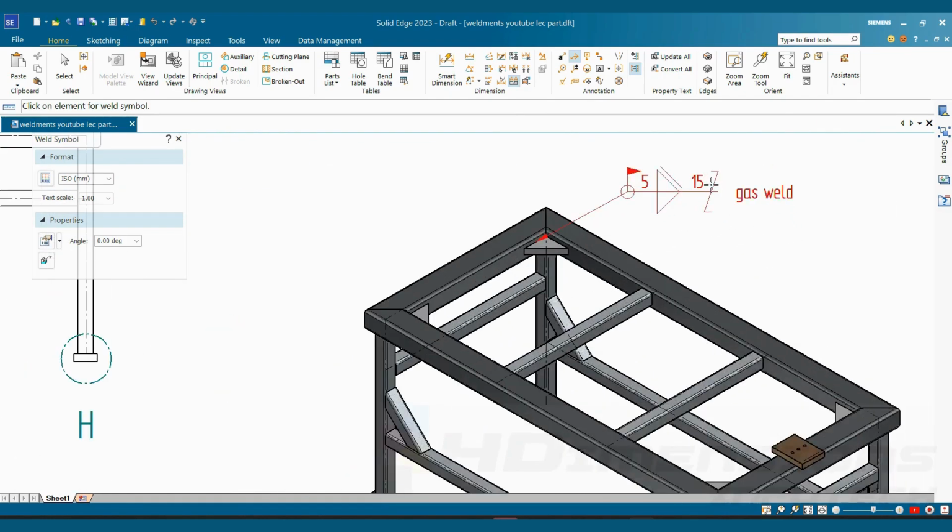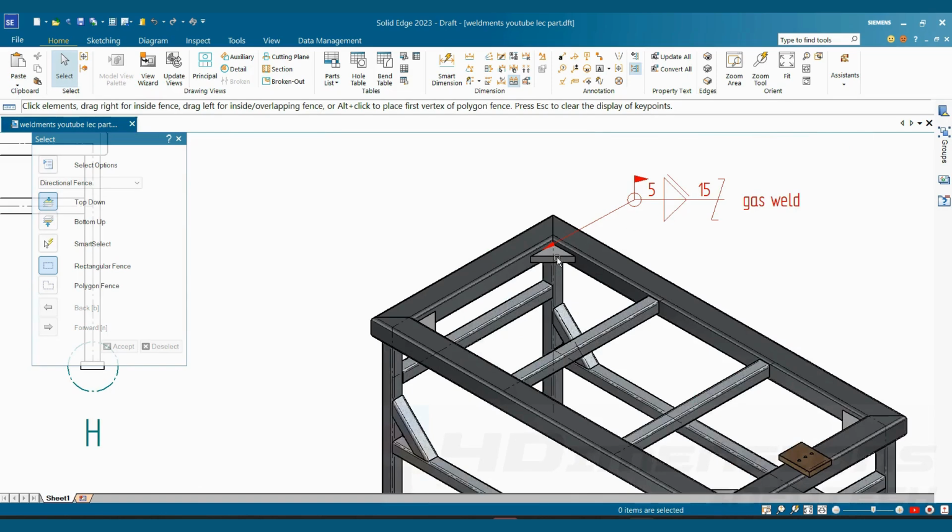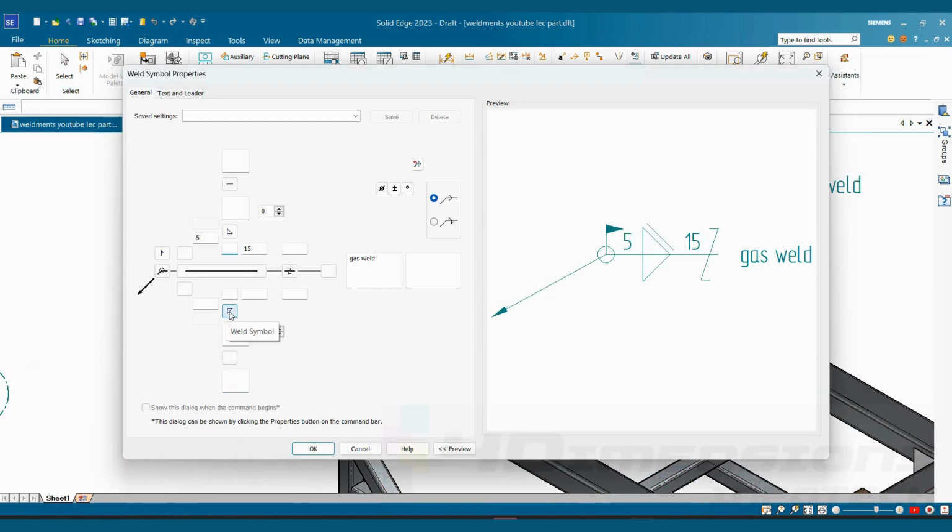You can see here, if I want a symmetric weld, meaning on both sides, then you just need to add the values here also. So I'll take it as 5. Same surface finish as contour only. Next, I don't want this intermittent symbol to be taken. I'll keep it flat only.